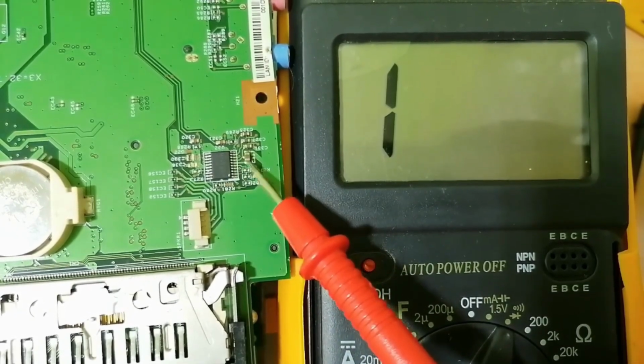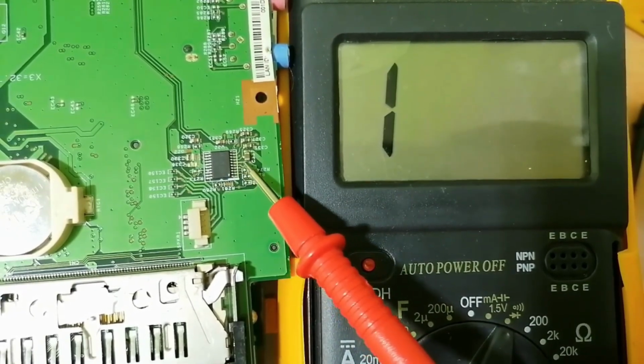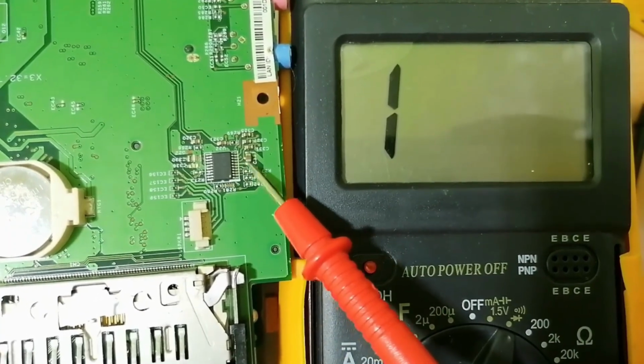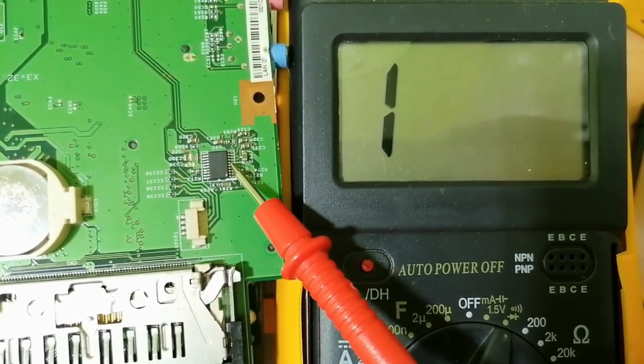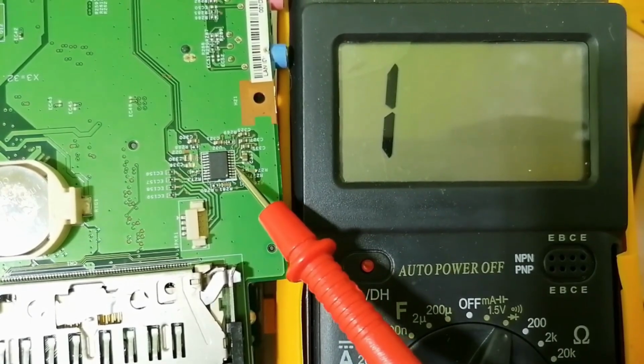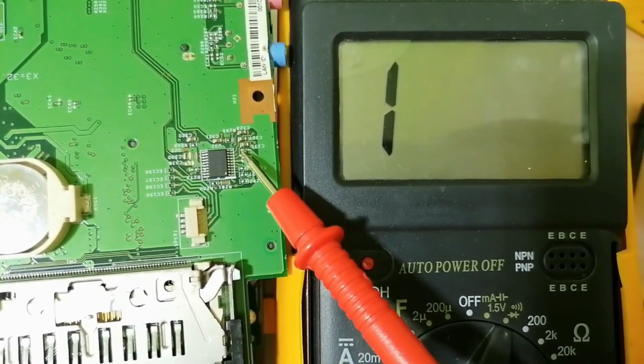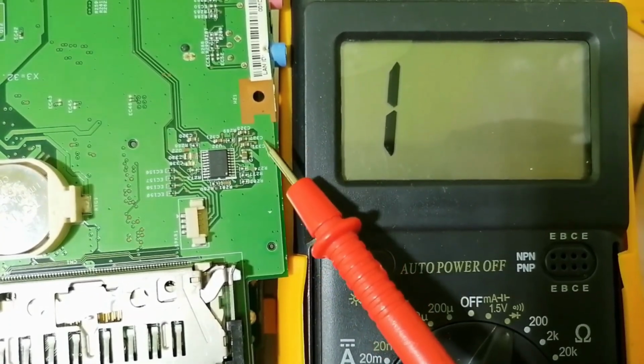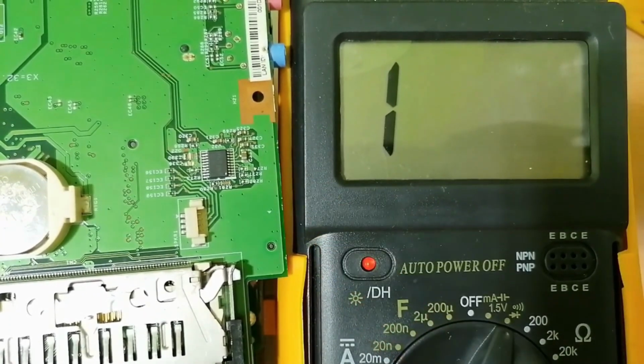Do you see this one? Here we have a bolded line, meaning the input for this IC is from here. So this pin of the IC is connected to this capacitor. As you can see, we have the path here, and the other terminal of the capacitor is connected to ground. We can even check using the multimeter.